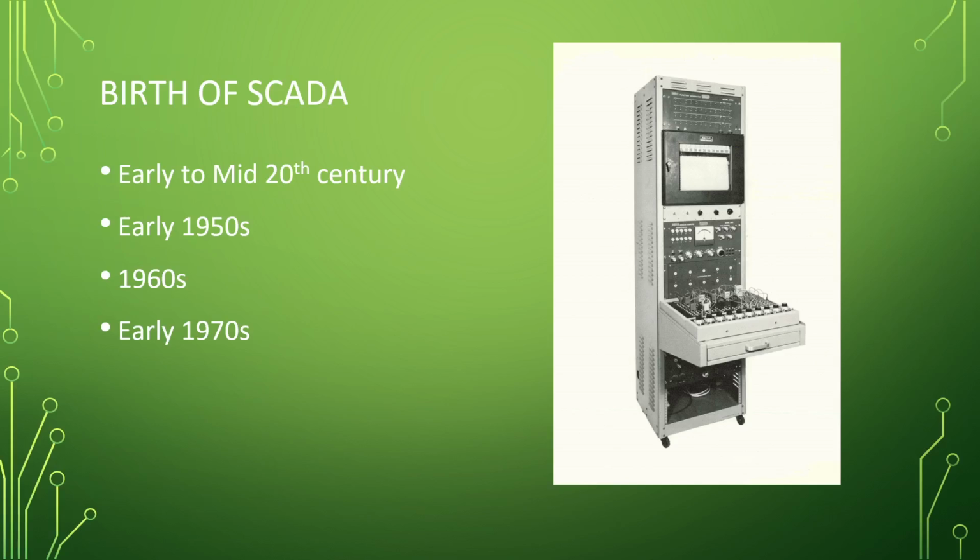So instead of having button A connect to button B, connect to limit switch C, connect to proximity D, connected to relay, connected to out, whatever, we have all of those connecting to the PLC, and in the PLC we write our code. We basically draw our wiring diagram. That way when you need to change something, you just have to drag a few symbols around, and Bob's your uncle, you're good to go. So yeah, it makes life so much easier having a PLC on board.